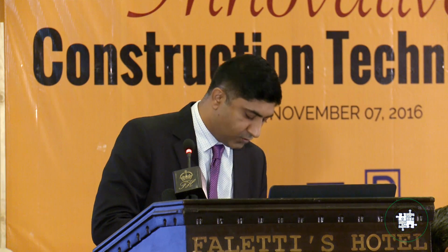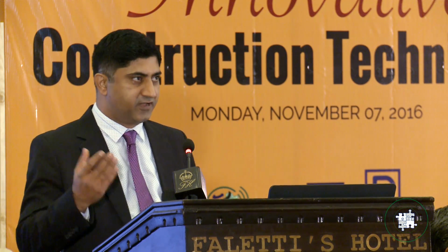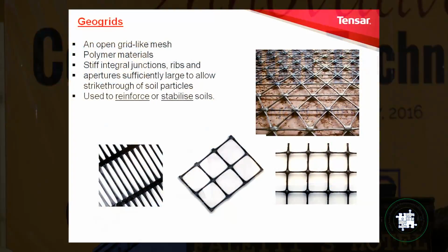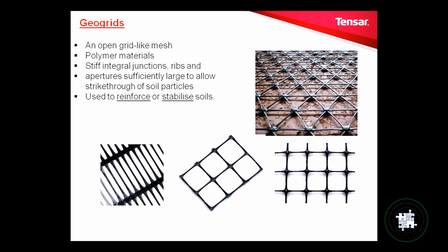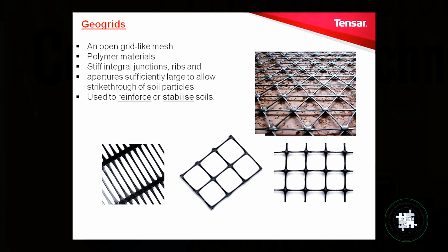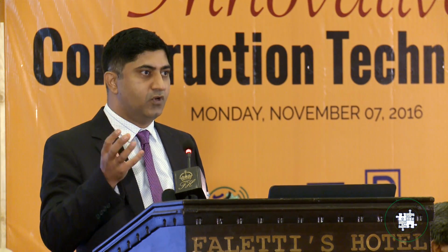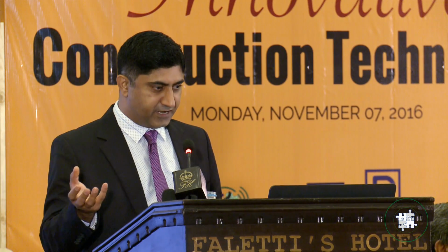So for those who don't know the geo-grid, what is a geo-grid? When I say geo-grid, some people may not know what it is. This is an open grid-like mesh structure made of polymer material, HDPE or PP. It is stiff. It has stiff integral junctions, and the ribs and apertures are sufficiently large to form an interlock with the construction material, which is the aggregate.